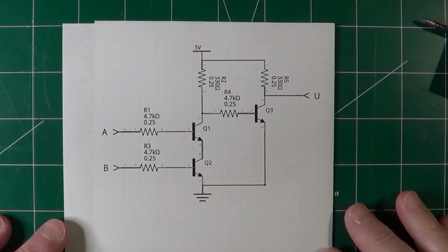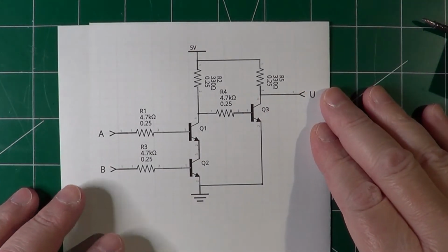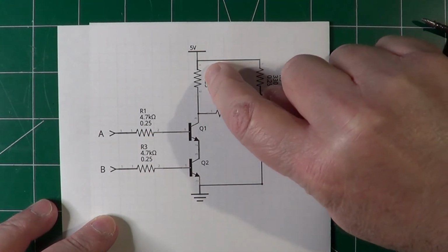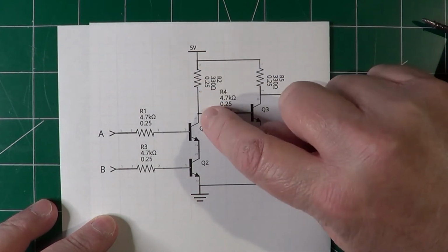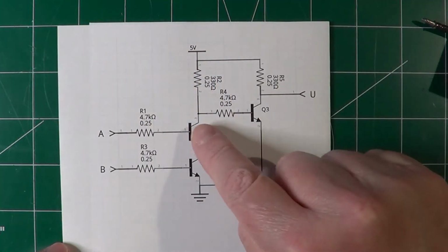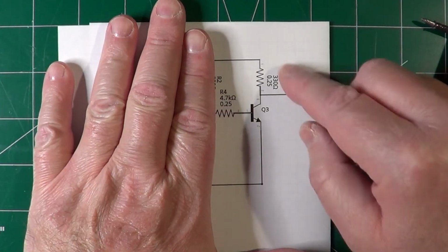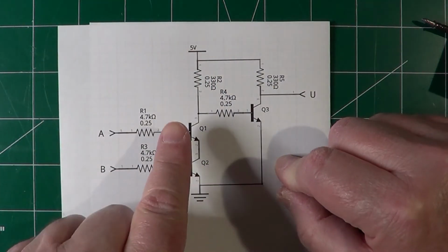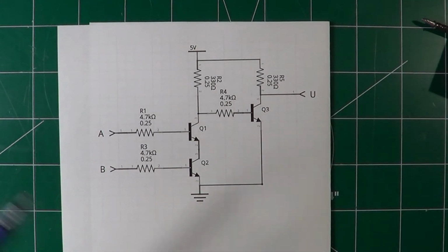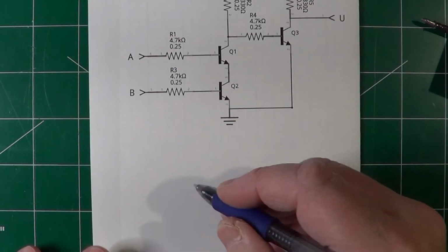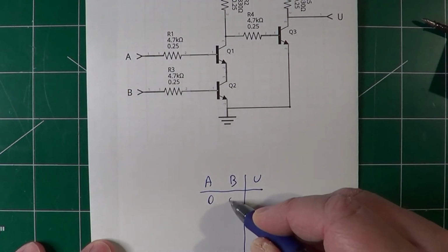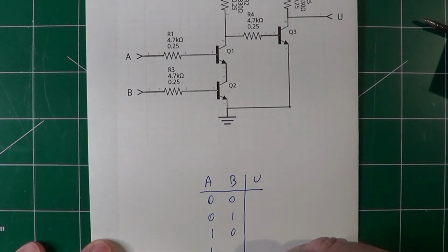And this is the circuit printed on paper with actual components. Again, we have this left section with its two transistors, the two resistors on the bases and the resistor on the collector, which act as a NAND port. On the right side, we have an inverter circuit, whose input is fed by the NAND output, and so it negates the NOT on the NAND. The output of the circuit will work therefore as an AND function. Let's now write the truth table for this circuit with two inputs A and B and one output U, and let's write all the possible combinations of inputs.